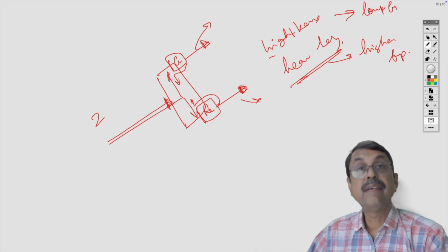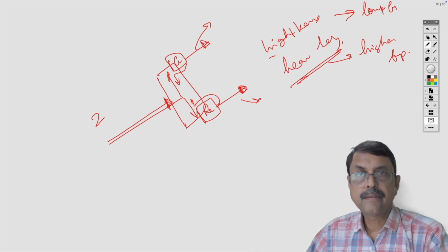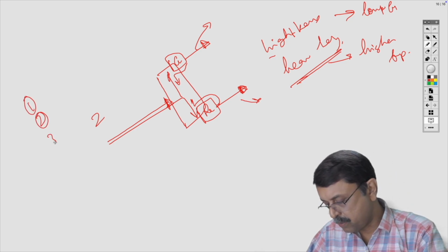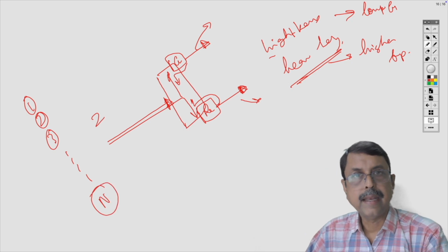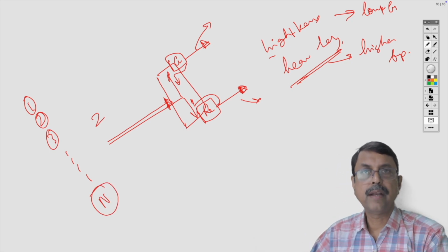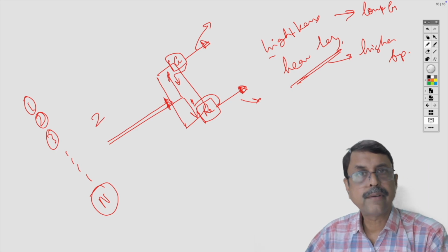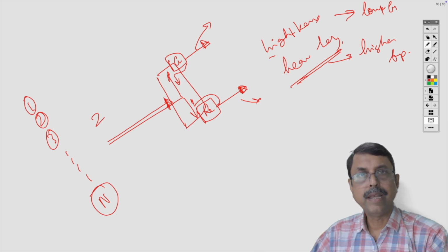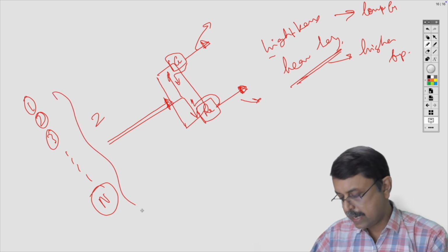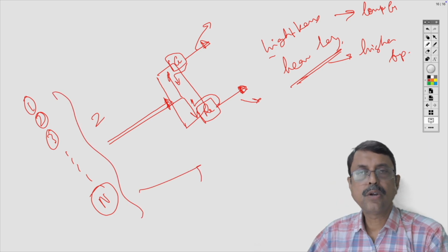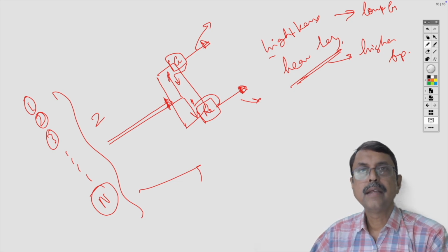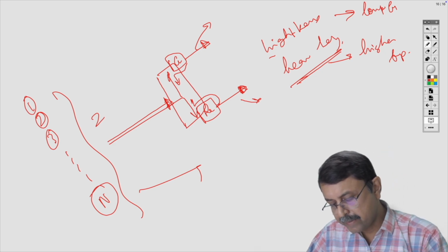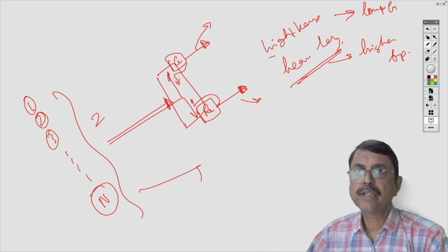Even if we have more than two components, that is a multi-component mixture, say component 1, component 2, component 3 and up to component n, it can also be distilled provided the components have distinct boiling points. It can be sent to a multi-component distillation column, and each component can be separated as per our requirement. So Aspen Plus has the option for multi-component distillation columns.